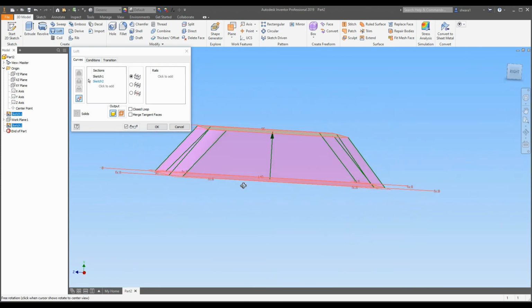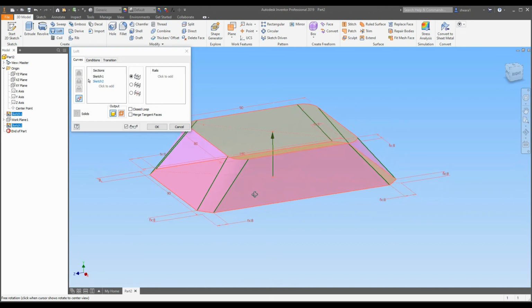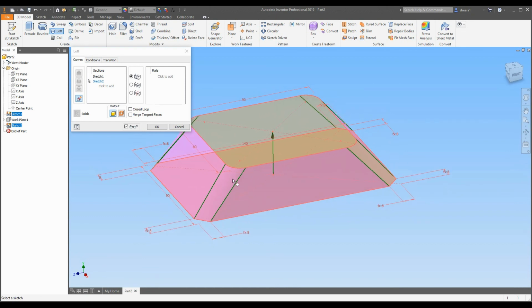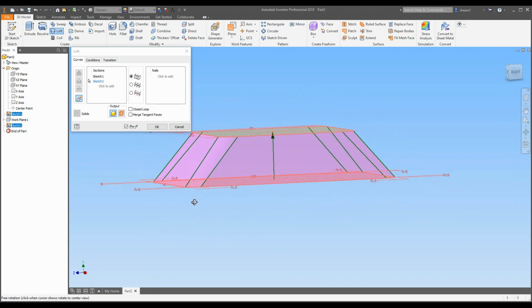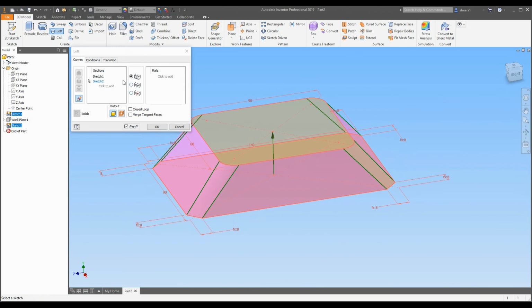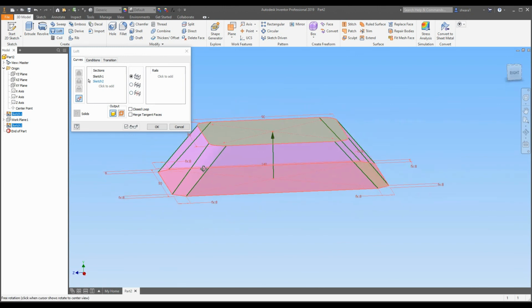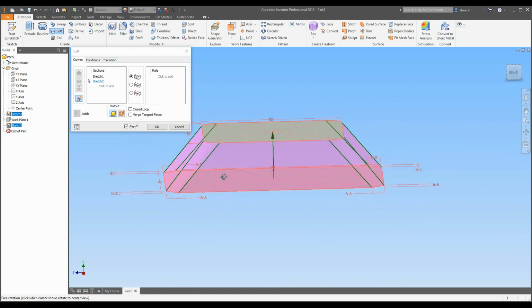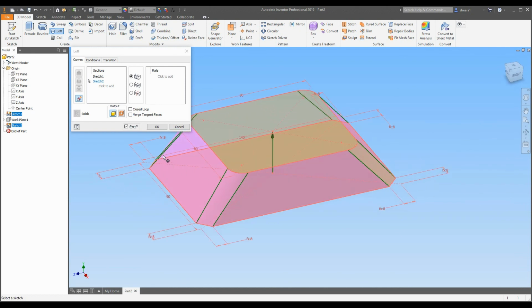It connects two shapes with an angle, and it creates a sort of nice smoothness between them. Now, it does look rather boring right now how these are still straight edges. So if I wanted to make this a bit more curvy, a bit fancier looking, I can go up here, just keep in the Loft menu here, make sure you have everything I have selected here, keep it on rails, go to the conditions dialog box here up at the top, and you'll see we've got two sketches.